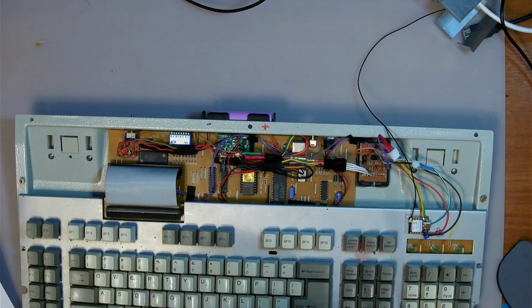So obviously there's an untold thing that I hadn't seen before, that if you're not connected to USB, you simply pull the data and clock signals low, and that, I guess, signals to the keyboard that there is nothing connected, so don't output any data or something like that. It's kind of interesting. And so at that stage it started working.